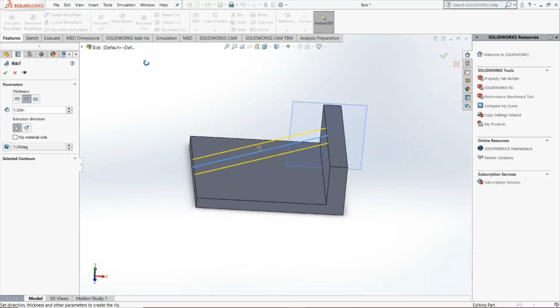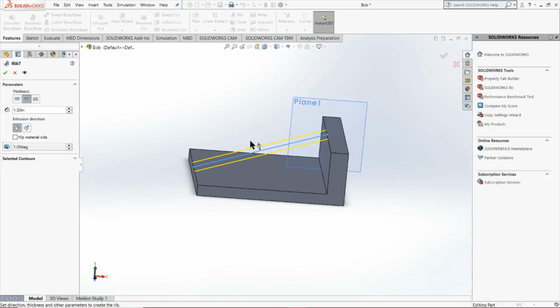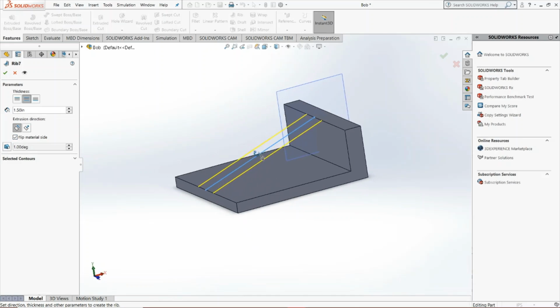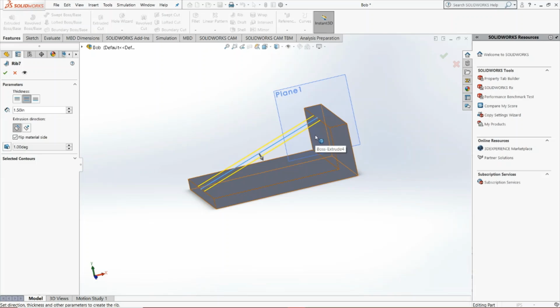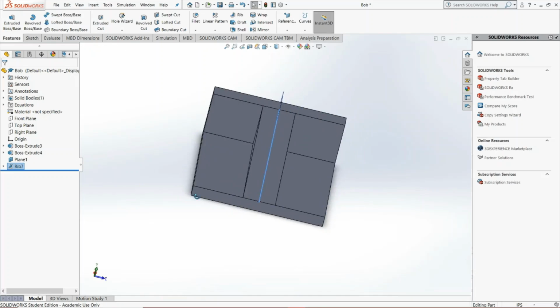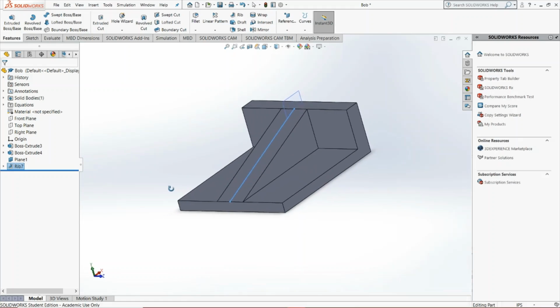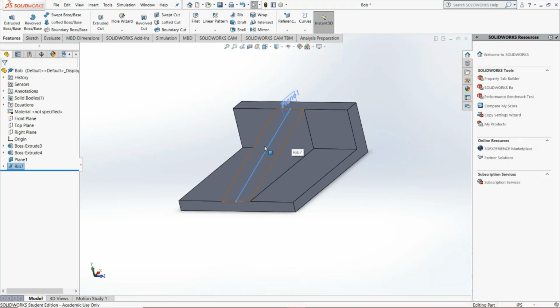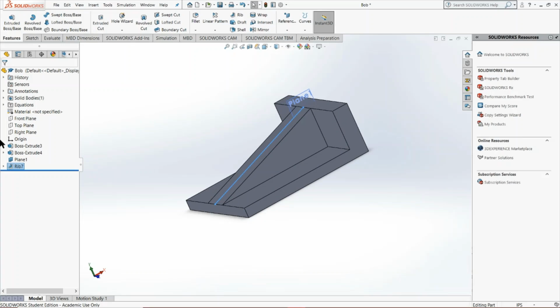And currently the material side is on the wrong side. We need to flip that. And the logic behind that is you have to imagine it's almost going to be like a triangular block going down onto this bottom portion of this L section. So if we press OK, you'll notice we'll have this wedge of sorts. So this will save you a lot of time rather than having to keep extruding or keep using sweeps to create random supports. It'll automatically detect where to end.